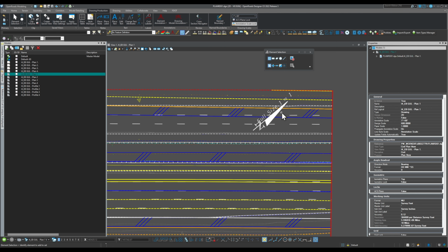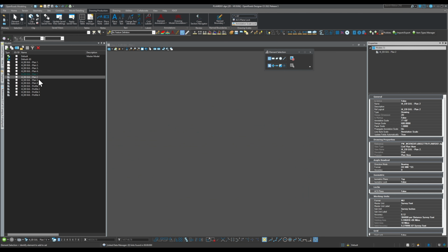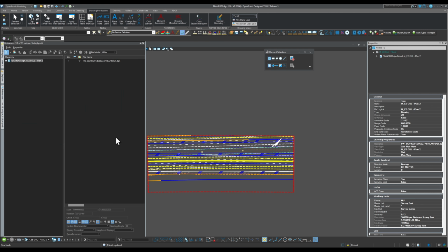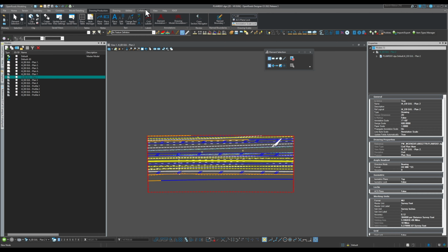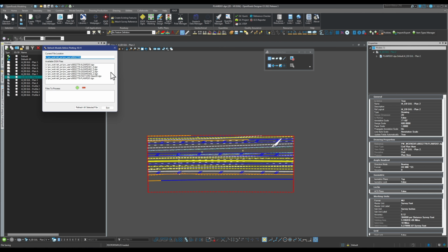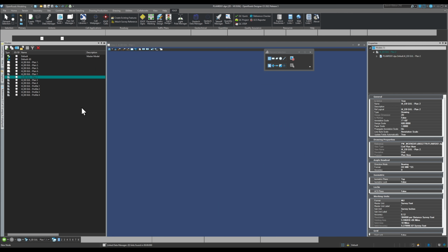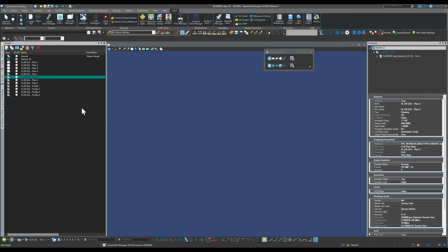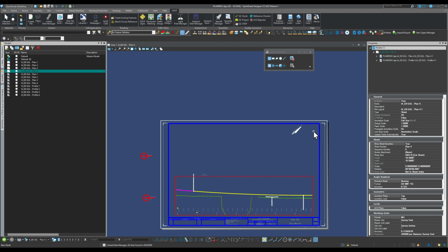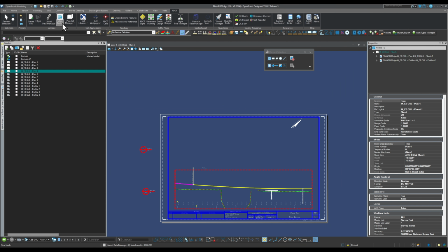As you can see, you drop it here one by one. It's a glitch. You just have to go one by one and open them, and it will work. Or, again, this is unique to Florida: you can come here. They have something called refresh model. So if you click on that and then add this one, select refreshed model. I don't know if it's going to do it. It's going to do it only to the sheets. Yeah, unfortunately, the drawing models we have to do by ourselves. Yeah, you see it still. So yeah, this tool only works on sheets.